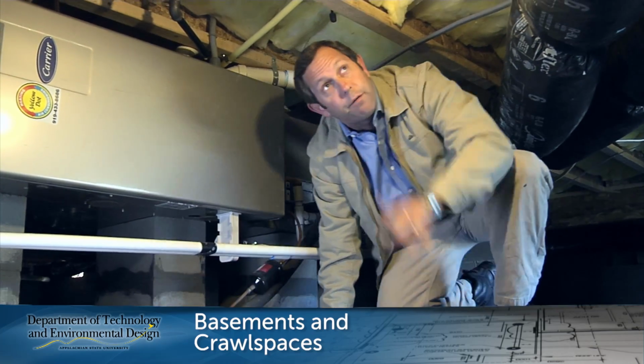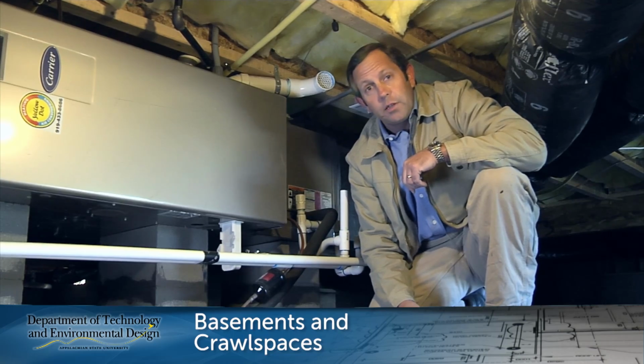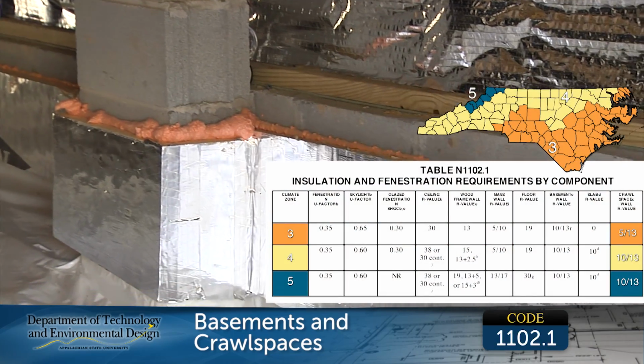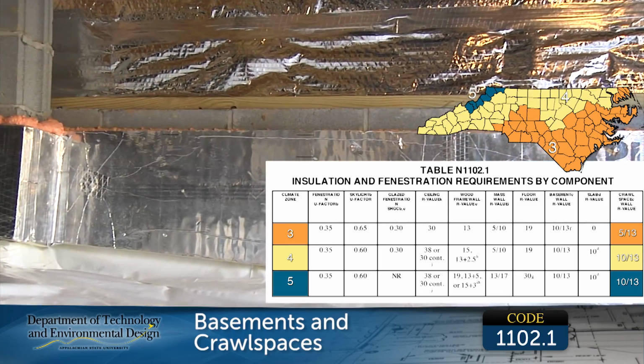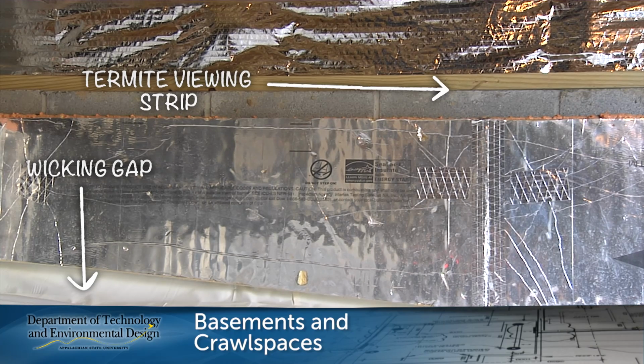While we're down here, basement walls can be insulated to R10 on the outside or inside using foam board, or R13 when using the standard wood frame cavity fill method. In a crawl space setting, the floor can be insulated if desired. But if the wall is chosen for insulation, you must again refer to Table 1102.1 for R factor guidelines depending on your climate zone. By the way, termite inspection clearance and wicking gaps are allowed without energy penalty.